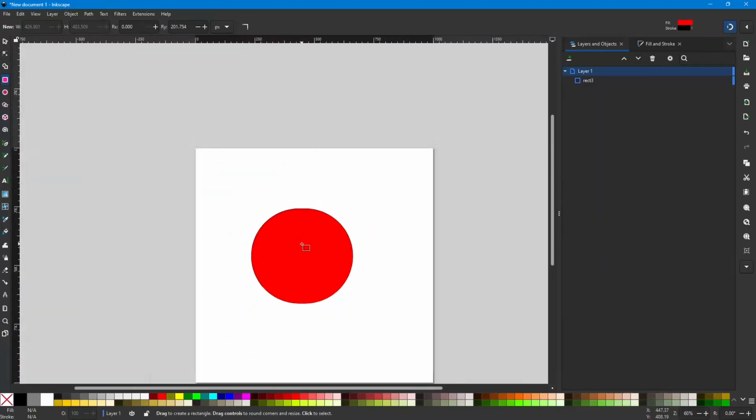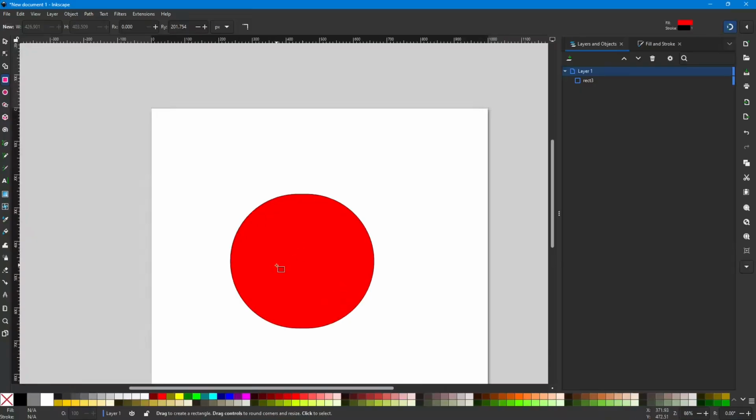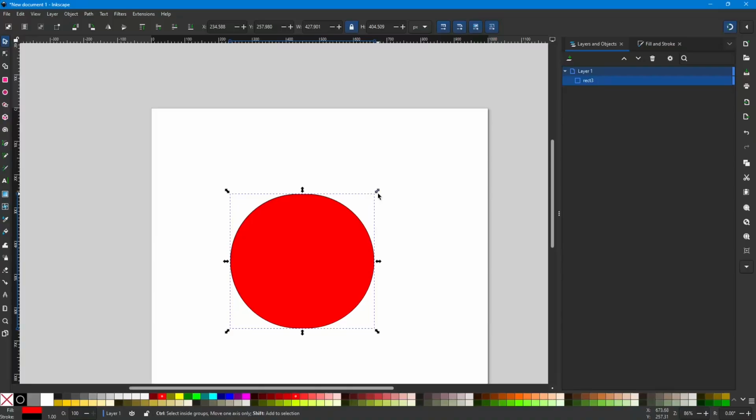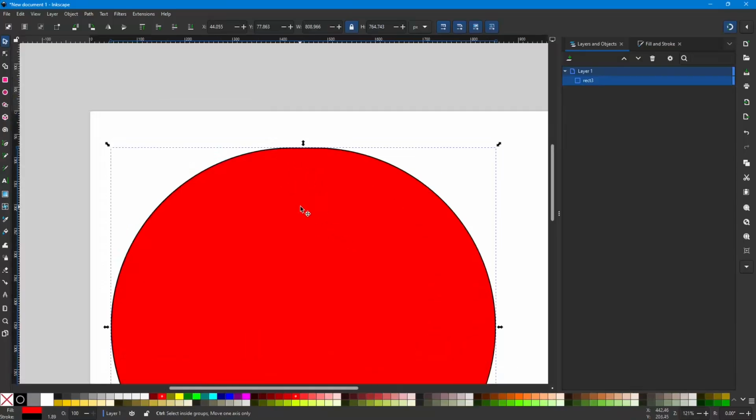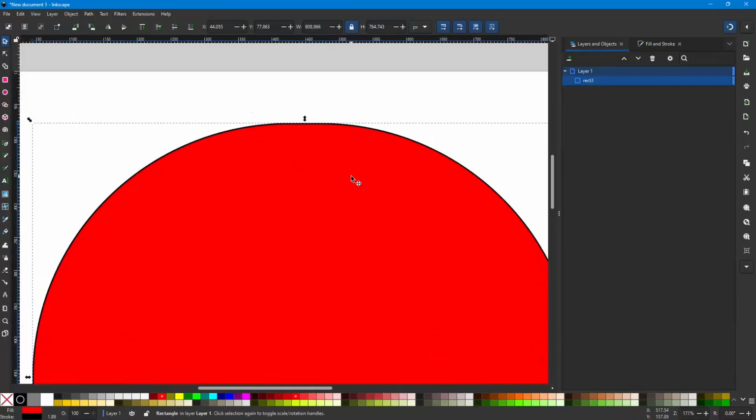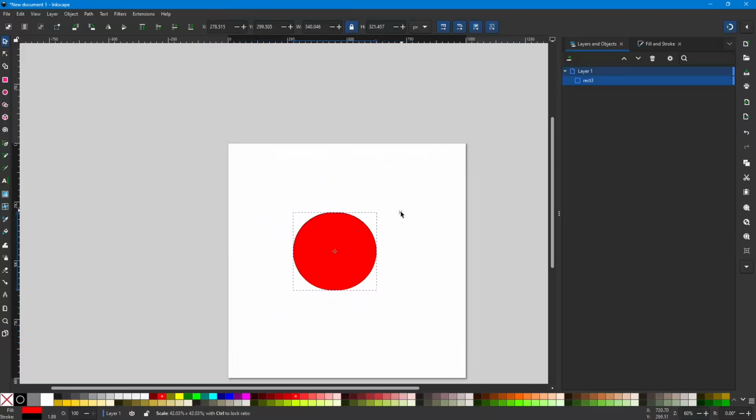If we were to go back to the selector tool here, just by hitting S and then select it, and I scaled this up, it still scales up, but it's still got that flat edge on it. So now I'm using the selector tool, but if I want to go back to the node tool, which is basically the tool that allows you to put the rounded edges on it, I can just either come up here and click the tool, or if you notice there, it has an N on it, so that means that's the hotkey or the shortcut key.